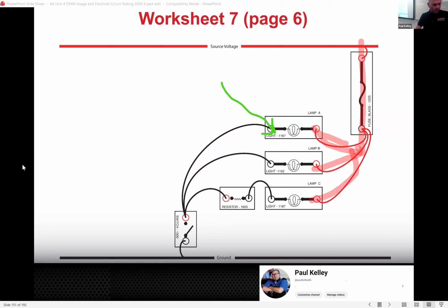All right, but let me redraw this and close the switch. We just closed the drawbridge. What happens here, well, I guess I shouldn't tell you. What do you think I should have at this point? At the green point right here. Now I should have 0, right? Cool, because now when I close that drawbridge, these electrons are like, we're out of here, it's closed, I'm gone. Okay, cool. Normally, honestly, this is how we test the circuit. But sometimes just to understand, if you have an open ground, the voltage will go all the way to the open point. So if you have voltage on the ground side, it's because the ground is open. It's just the way it is.